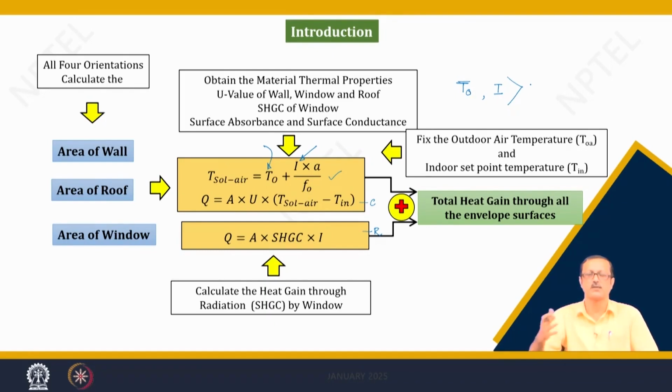the total amount of cooling load required, and estimate the total capacity of the air conditioning unit, over the period from 10 to 5 or whatever the particular period of time is. We have to see how much the total heat gain is, and that total heat gain will be equivalent to the cooling load. That much cooling is required in a tropical country like India. So, that will give an estimation of how much energy is required to cool down the particular environment, that is, the indoor environment.